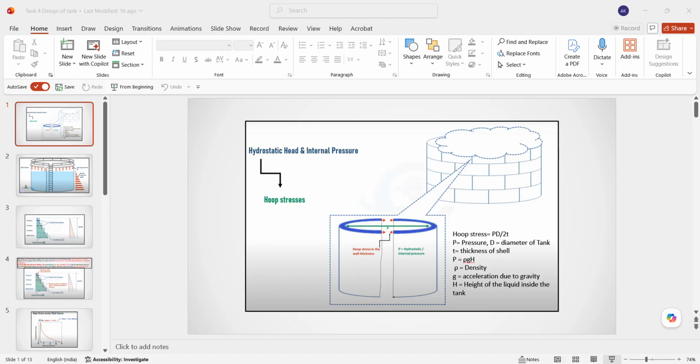Now, when to use the variable design method and when to use the 1 foot method. The variable design point method may only be used when the purchaser has not specified that the 1 foot method be used only, and when the following is true: L by H is less than or equal to 1000 by 6. Where L is equal to what? L is equal to 500 D, D is the diameter, T is the thickness, to the power 0.5.